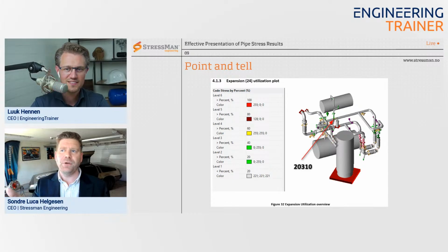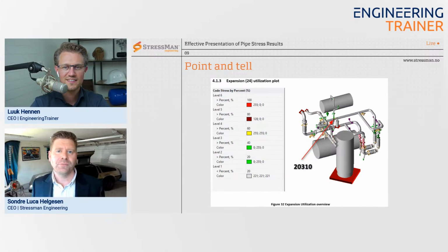And then it might be okay, but you didn't write about this in the report, for example. You added the flexibility of the pipe support, totally fine. But you did not write it that clearly in the report that you included it, for example. Maybe I could see it in the input echo file.